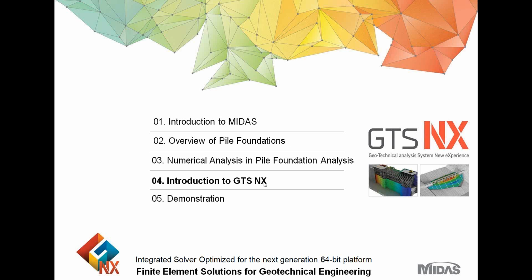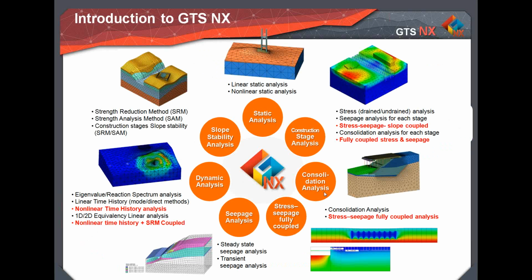Okay, so now going back to the presentation. Just give a second for the page to load. Now let's go into a little more detail about what you can do with the program. Any static analysis or nonlinear static analysis is typically used for excavations or shallow foundations. Any construction stage sequencing can be done with the static analysis capabilities. There's also consolidation analysis if you're looking at immediate settlement or consolidation for clay soils. The program handles that, and then stress seepage fully coupled analysis.